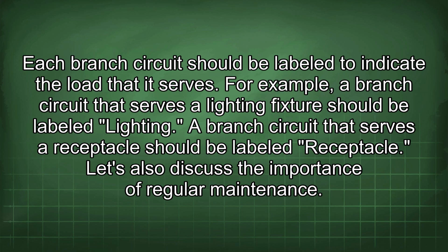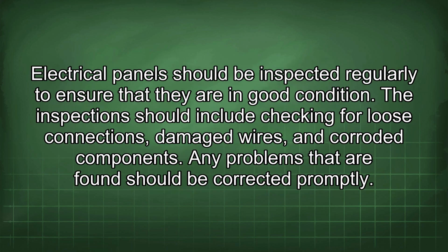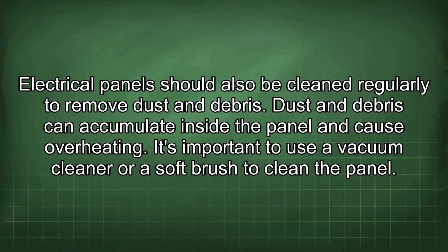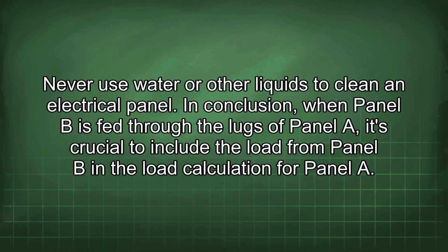Let's also discuss the importance of regular maintenance. Electrical panels should be inspected regularly to ensure that they are in good condition. The inspection should include checking for loose connections, damaged wires, and corroded components. Any problems that are found should be corrected promptly. Electrical panels should also be cleaned regularly to remove dust and debris. Dust and debris can accumulate inside the panel and cause overheating. It's important to use a vacuum cleaner or a soft brush to clean the panel. Never use water or other liquids to clean an electrical panel.